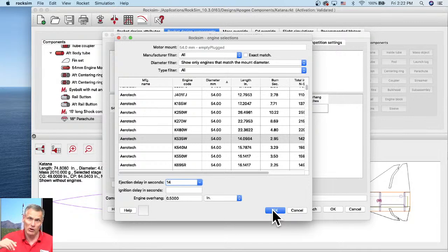And then the big parachute, we want it to deploy closer to the ground, anywhere from 200 feet to 800 feet. If you're doing this for the first time, you probably want to set it higher because you need to learn how long it takes for your parachute to open. Because some parachutes, the way you pack them is going to determine how fast they open.